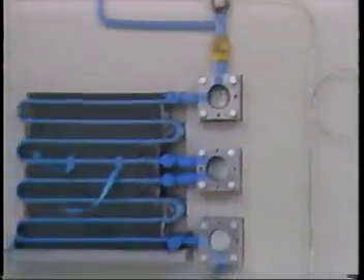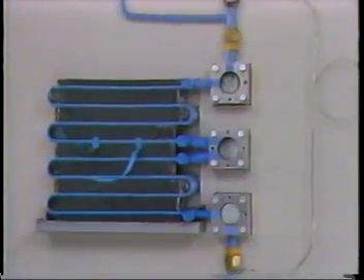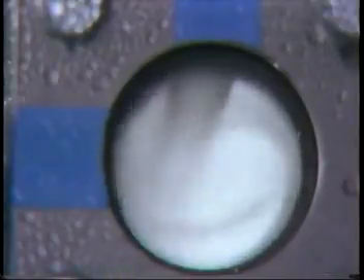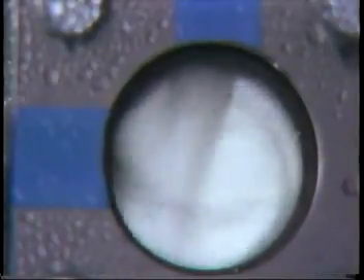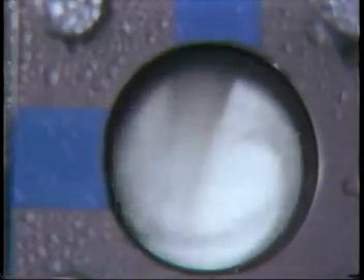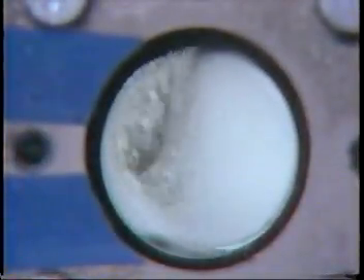What happens in the evaporator then? When there is not enough refrigerant in the system, a greater portion of the refrigerant is a gas near the entrance to the evaporator. And most of it is a gas in the middle of the evaporator.